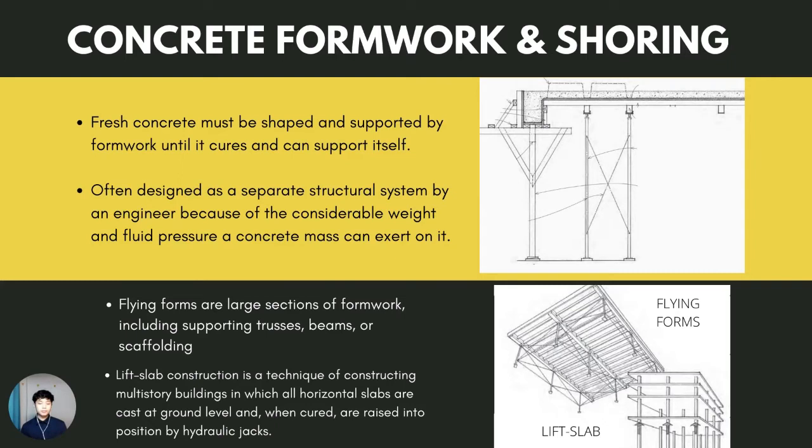Under the flying forms in the diagram is the lift slab. Lift slab construction is a technique of constructing multi-story buildings in which all horizontal slabs are cast at ground level, and when cured, the slabs are raised into position by hydraulic jacks.